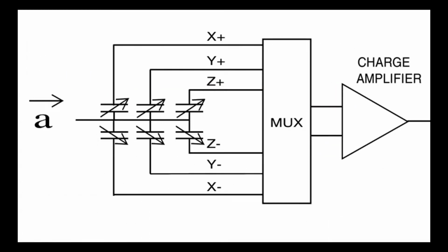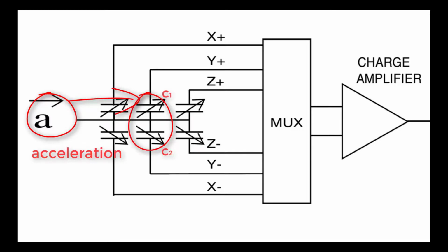The block diagram shows that the input to the device is acceleration that feeds the X, Y and Z vector inputs. In this case, we'll examine the Y input. The moving bit is a piece of metal that is really the bottom plate of capacitor 1, C1, and the top plate of capacitor 2, C2, joined together. As the iPhone tilts, the metal moves. When the metal approaches the top plate, the capacitance of C1 is increased, and as it falls to the bottom plate, the capacitance of C2 is increased.